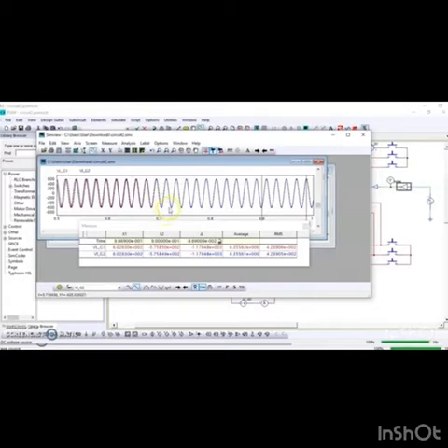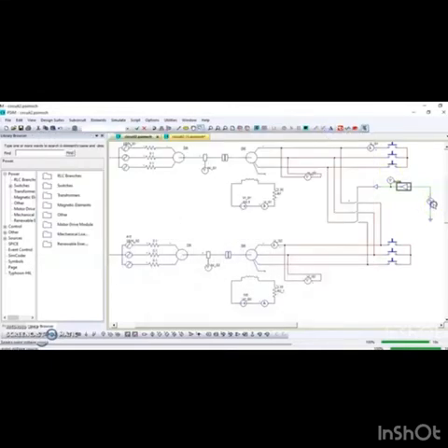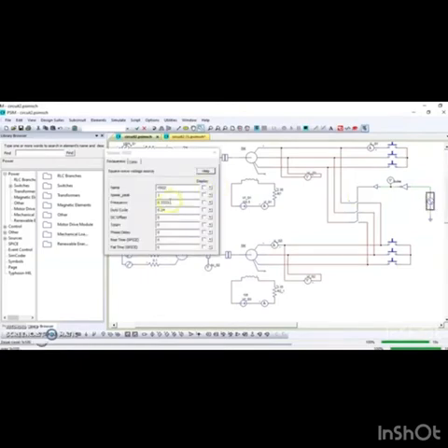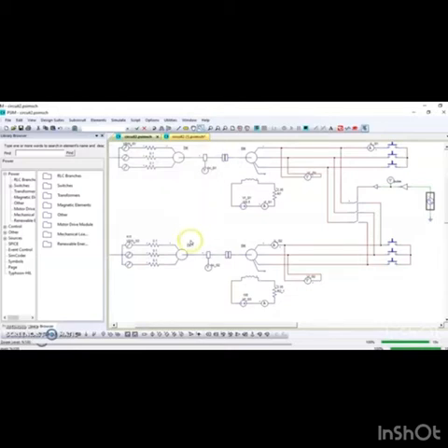The frequency of generator 1 must be slightly higher than the frequency of generator 2. Lastly, at the square wave source, the frequency is set to 0.33 and the duty cycle will be set to 0.24. Since the suitable time for two generators to connect in parallel connection is 0.71 second.